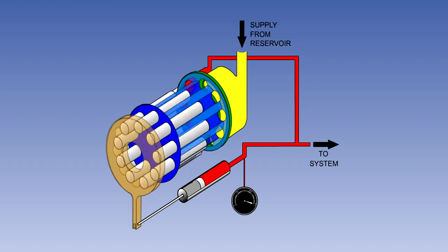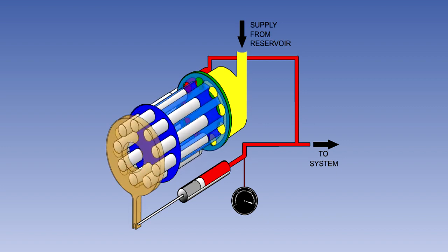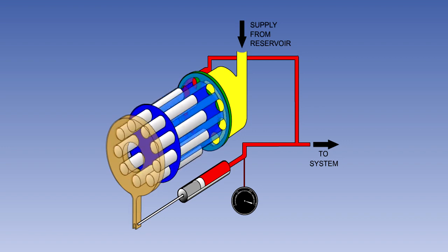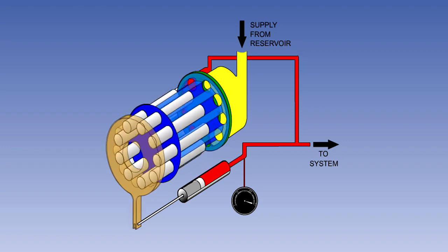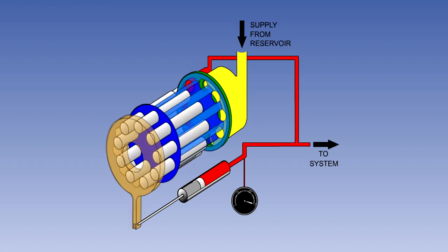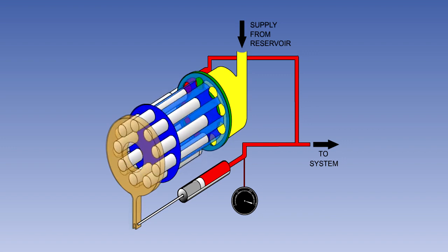When normal operating pressure is reached, if no surfaces are being operated, the swash plate will be almost vertical, the piston movement will be almost zero, and there will be only a small flow of fluid through the pump. This flow is for pump cooling and lubrication. It returns to the reservoir through the case drain return line.